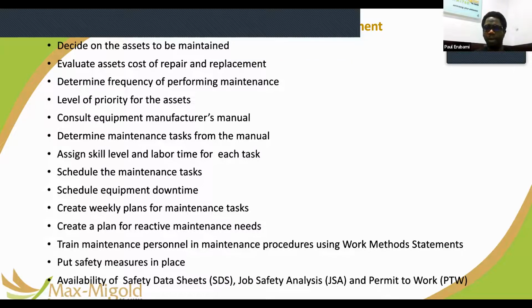So people are wondering, why exactly do you need to do this servicing now when we all just resumed for work? Why can't you do it when we are closing from work and when we are not here? Those are the kind of questions that are asked because you are not doing a maintenance plan. Because if you are doing a maintenance plan, you are thinking of the impact of your own maintenance on the availability of the assets. And that's one of the things we picked up in the preventive maintenance strategy: you do certain things at certain frequencies, and if it's an asset that you have to take out of operation to do those activities, then you are creating downtime, occasioned by the maintenance activities themselves, not downtime that comes out of breakdown.